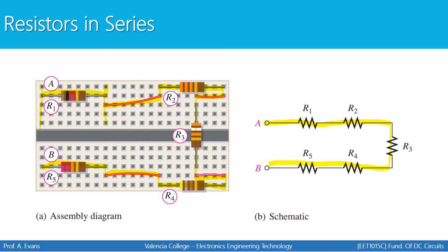It won't intuitively look like it is a series circuit, and we have to remember the operation of how a breadboard is designed underneath in order to create our circuits. So keep in mind that, again, if we want to form a connection, we need to have two terminals within the same column on the breadboard. That's what causes these to be connected, for example, and that's what allows the current to travel from R1 through the jumper wire and then into R2.